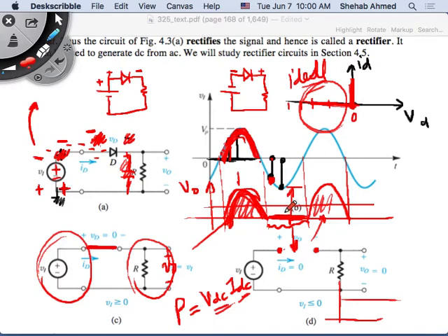But you've produced a waveform with an average value. This is one application. This is called a rectifier, and more technically, a half-wave rectifier. Why? Because it rectifies half the sine wave only, right? This is the simplest type of rectifier. Rectifiers are one of the main applications of diodes, especially on the power side: power conversion, adapters, motor drives, all power applications will have similar requirements.